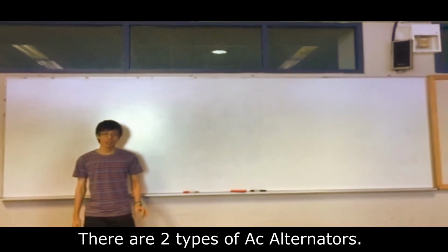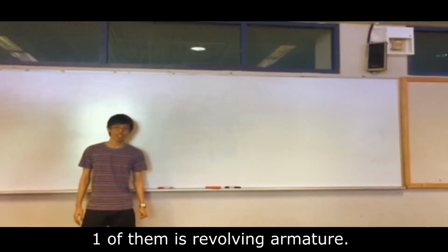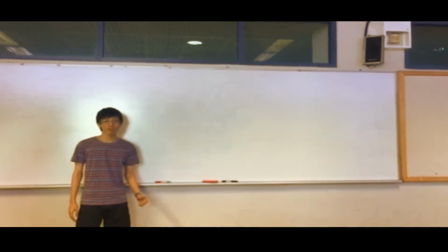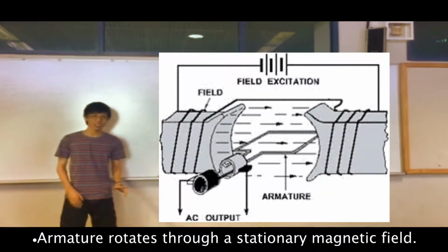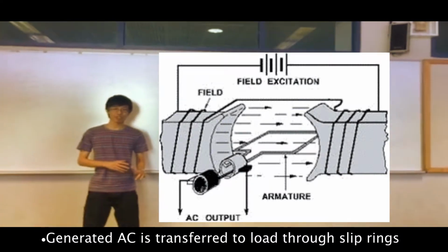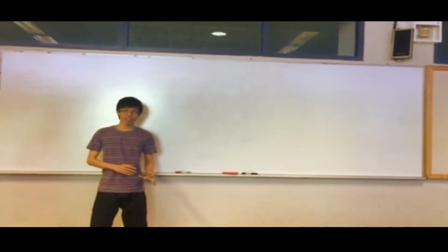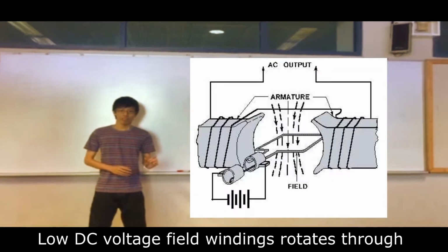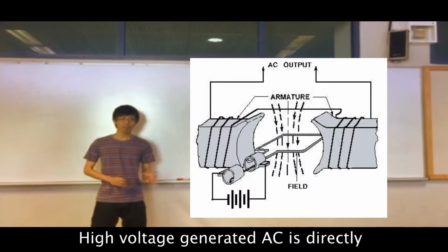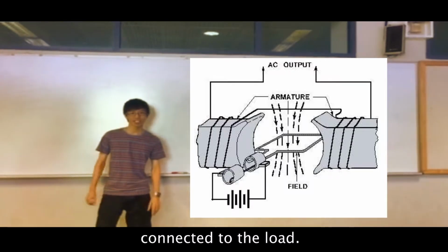There are 2 types of AC alternators. One is the revolving armature and the other is the revolving field type. For the revolving armature, the armature rotates through a stationary magnetic field and the generated AC is transferred to the load through the slip rings. For the revolving field, a low DC voltage field winding rotates through a stationary armature and the high voltage generated AC is directly connected to the load.